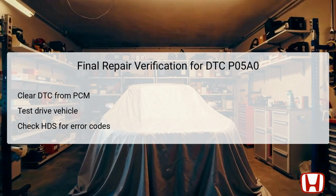Next, a test drive should be conducted to allow the vehicle to reach operating conditions where the shutter grille would generally be active. This real-world application helps assess whether the problem has been rectified successfully. Following the test drive, it's important to use the HDS again to ensure that no error codes reappear, confirming the functionality of the shutter grille assembly and the connected circuits is restored.